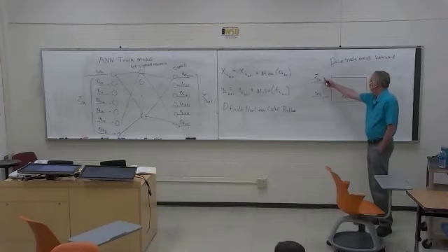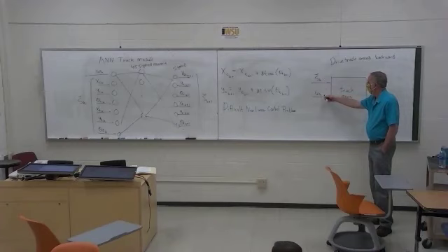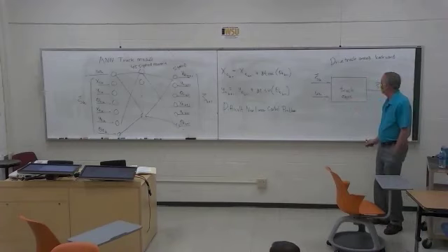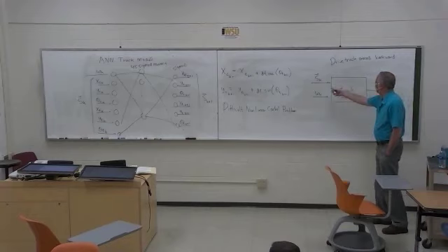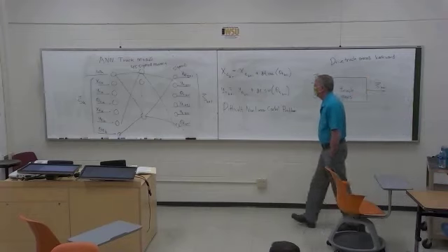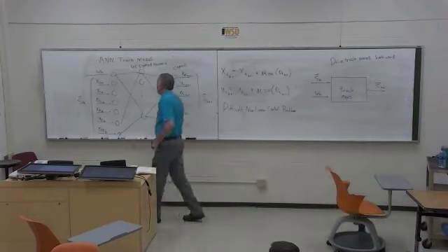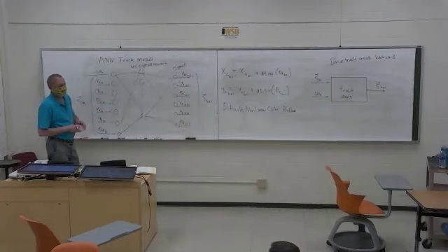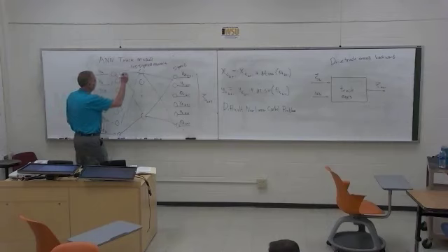We start out at different positions in the parking lot. We just do some wheel angles as the truck backs up, collect the data, where it ends up at the next time step, keep doing that. And that exactly is the training data that goes into the network. You don't have to do anything with it. Just collect time step data as you back the truck up. That's exactly what he did in the paper, he just backed the truck up a lot, collected the data and trained the system model.